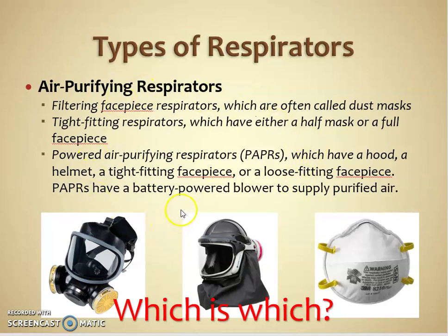Now, it's important to know that an air purifying respirator is useless in an oxygen-deficient atmosphere. As the name implies, air purifying respirators merely filter out pollutants or hazardous substances from the local atmosphere. However, they do not provide additional oxygen. So if you're working in a confined space that has an oxygen concentration that is lower than 19.5%, these respirators will be useless and you might experience adverse health effects pertaining to oxygen deficiency.